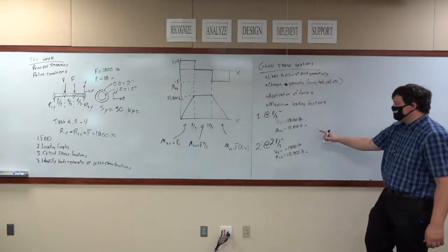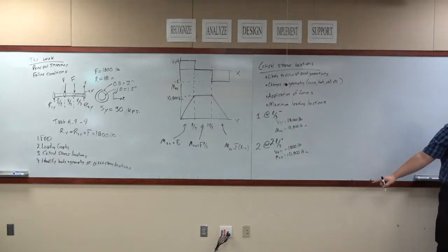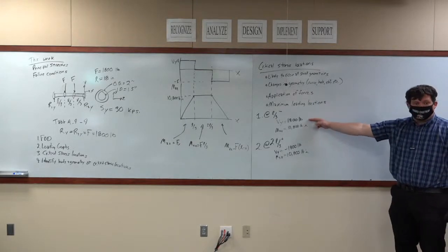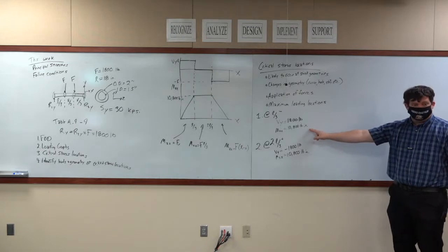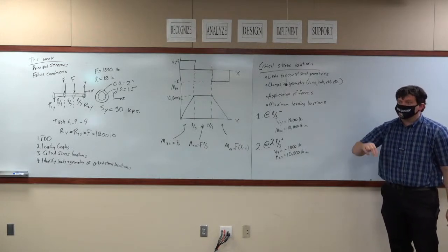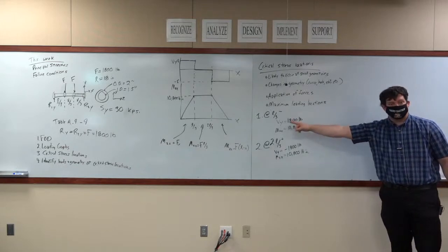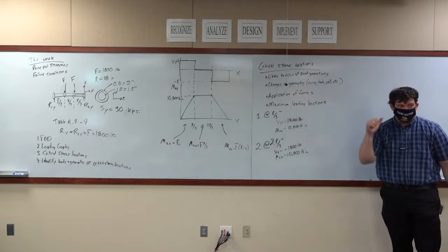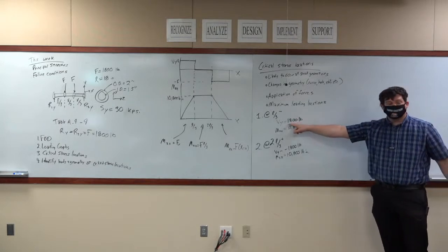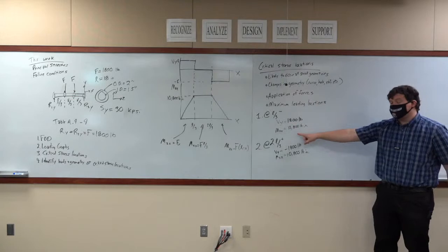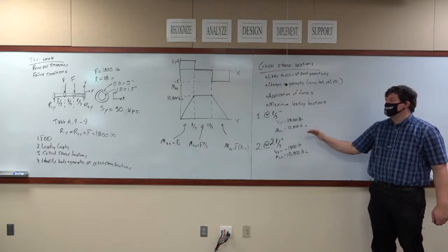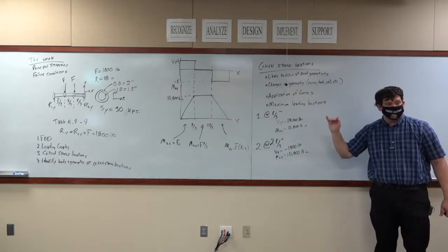So we've identified the loads. We don't have any other loads at this location, which means this is going to create a stress, and this is going to create a stress. But those are the only 2 loading conditions that are going to create a stress at L over 3. We don't have any axial, any torsion. We don't have any shear forces in any other directions. We don't have any bending moments in any other directions. We've listed every single loading condition that occurs at L over 3.